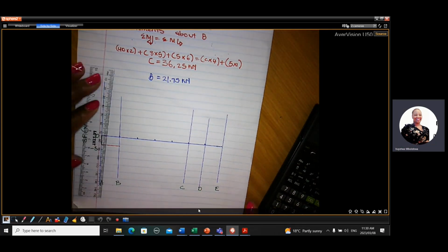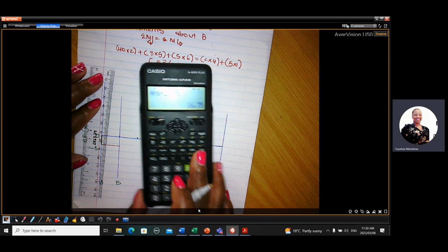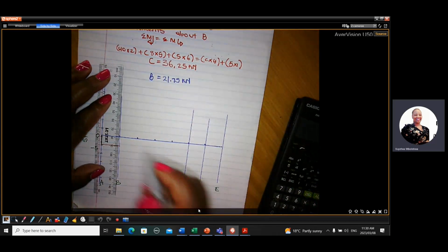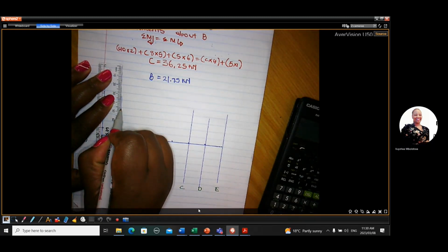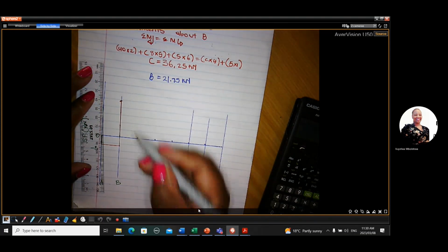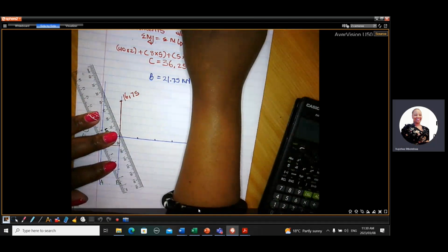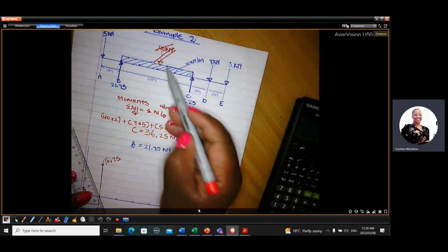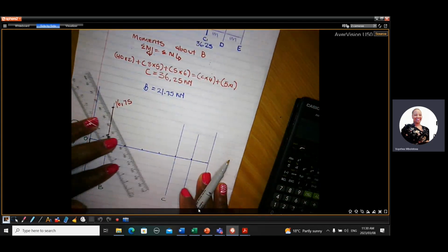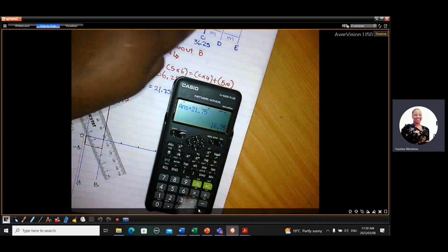And then at B, there's an upward force. We plus the upward force of 21.75. It gives us 16.75, a positive. So we go up to 16.75. Then that force we don't consider now as we are doing the shearing force diagram. That one, it was just to calculate the reactions. We are now at 16.75 FB, and the next force is the UDL.